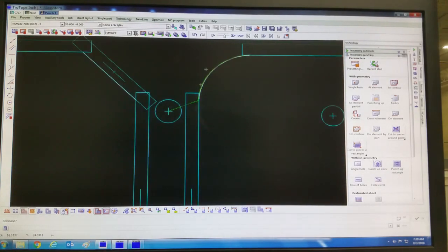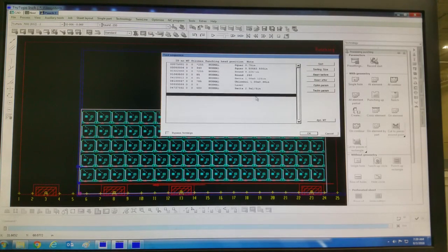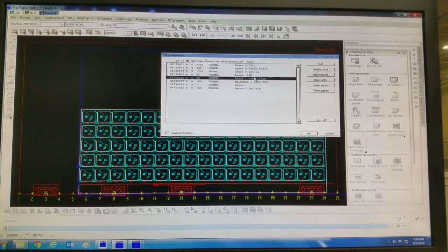So what is this tool? Okay, so this tool is quarter, okay? So and if I want to change the sequence that the laser cutting is first, I had to think a little bit deeper, because for the laser cut there is the pre-punch hole, this tool as the pre-punch, so this one has to be first.